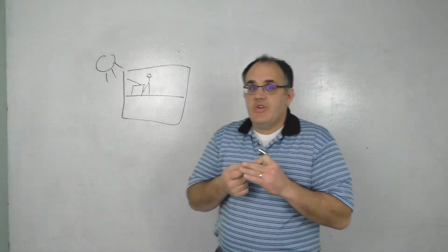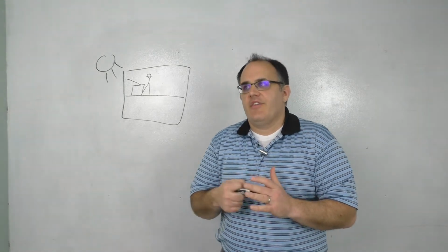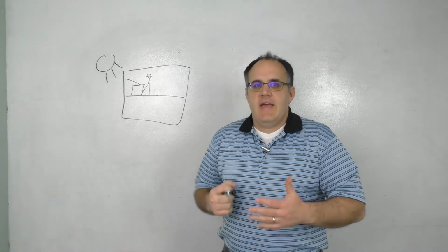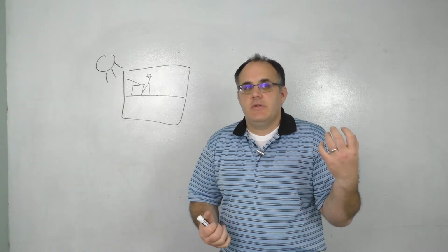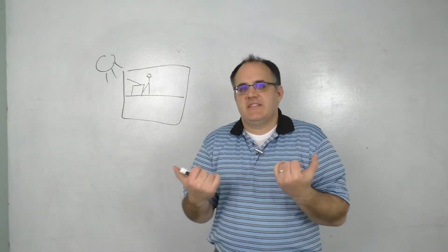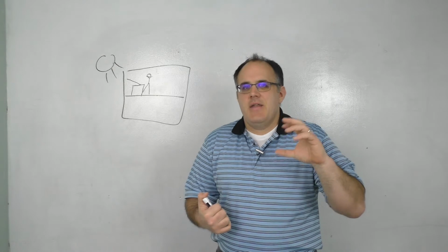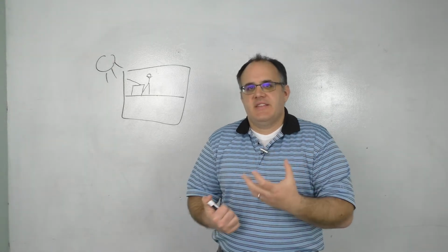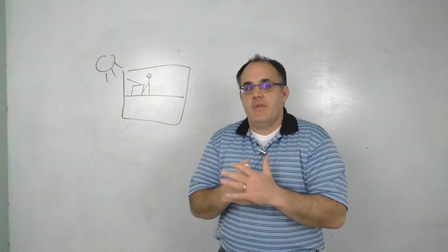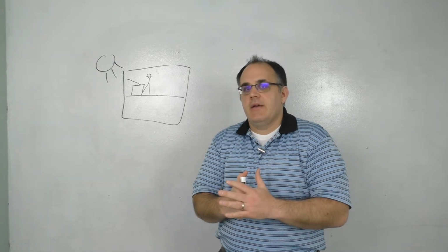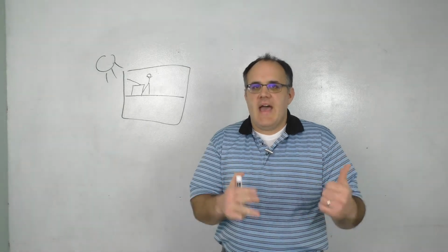Now, one thing that I really want to focus in on, it's something that is rampant in the industry, something that I've heard from my students that they are challenged by, and something that a lot of owners are challenged by. And that is the difference of optimization and retro commissioning. The two are not the same. Optimization seeks to take a sequence and modify it to perform the same outcome more efficiently. Hence our economizer example earlier. Whereas retro commissioning seeks to validate that the existing sequence is performing as designed.